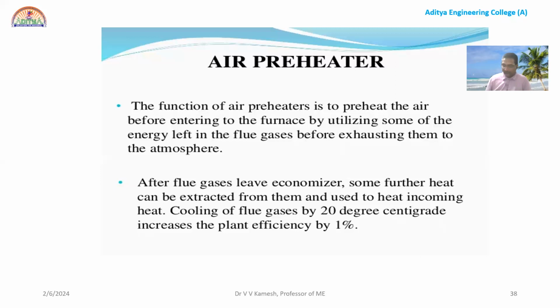So air preheater, why do we need to heat the air? You see, in the boiler, coal is fed through one system and we are supplying air for the burning of the fuel, right? If you supply hot air, your efficiency will increase.